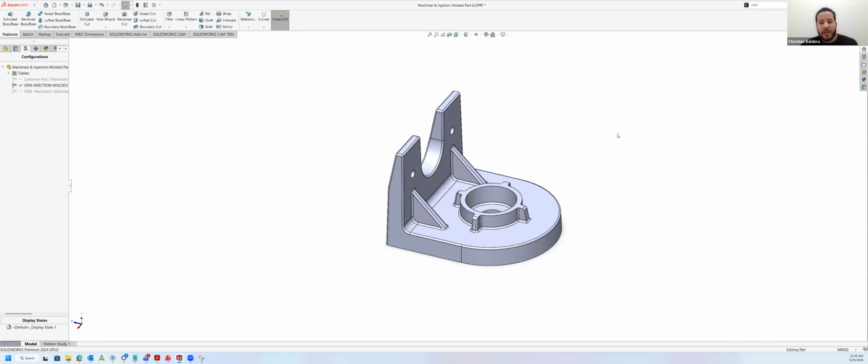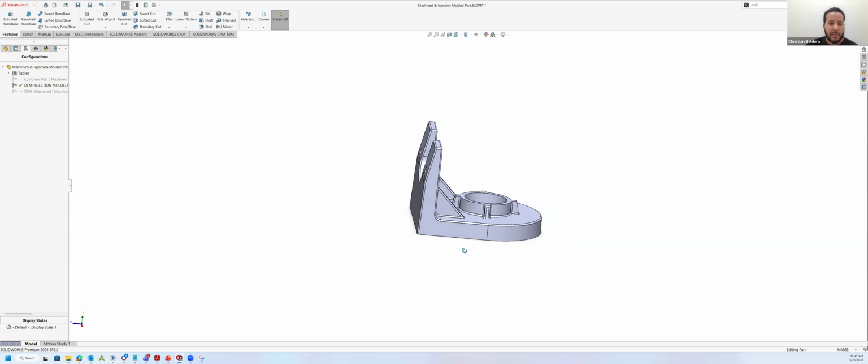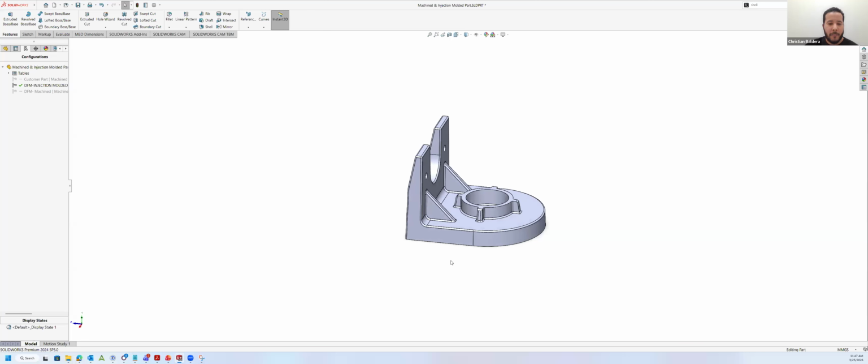Assuming this, you'd mentioned that you'd most likely be sticking with this design shown on screen for 3D printing. For supporting that vertical extrusion, would you really include those webs there for 3D printing, assuming that's the print orientation you're going to go with, or would it be better to just increase that internal fillet radius?